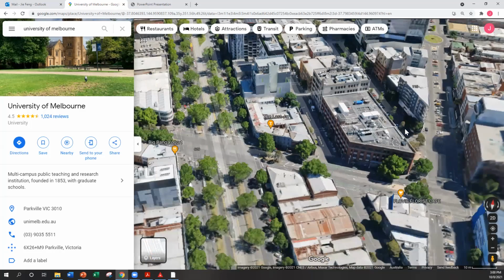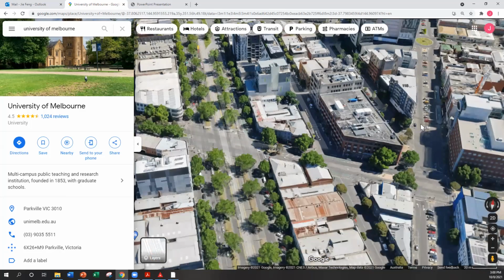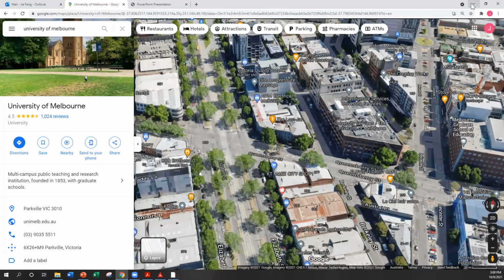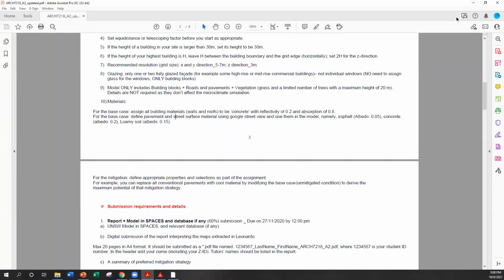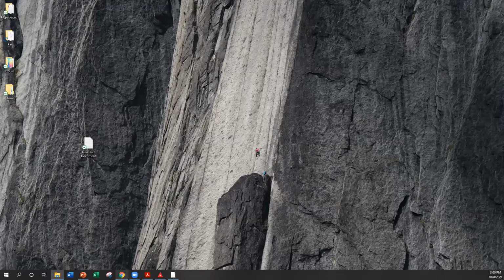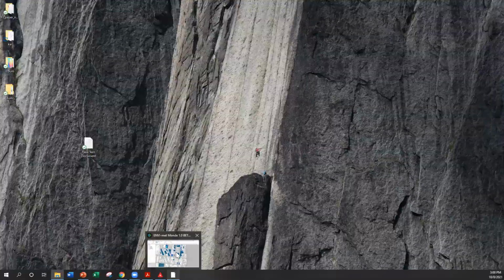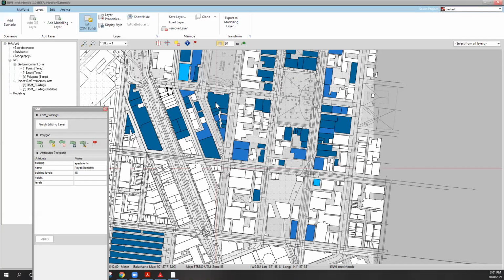Okay. So we don't get the exact data, right? Because we have the limit from OpenStreetMap. For some of the buildings, those original ones, let me show you, they come originally with a building height from OpenStreetMap. We don't need to do that part, but for all the buildings that don't have such information, we have to manually assign the height value. Okay.